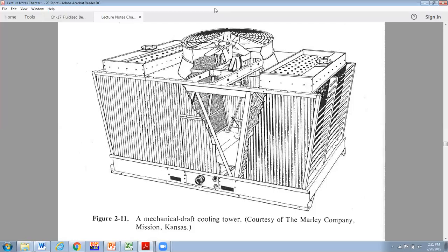So I think we said in class the other day, the standard numbers for an HVAC cooling tower, at least the old time numbers, were 95 degrees in, 85 degrees out at a 77-degree ambient wet bulb. That would be the design condition, the design wet bulb. And the tower would be big enough to be able to do that for the heat load that was going to be put on it: the chiller capacity, plus the compressor power on the chiller, plus any stray heat transfer that would get into that condenser water would need to be rejected by this cooling tower.